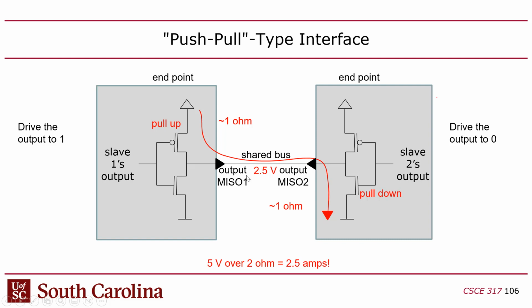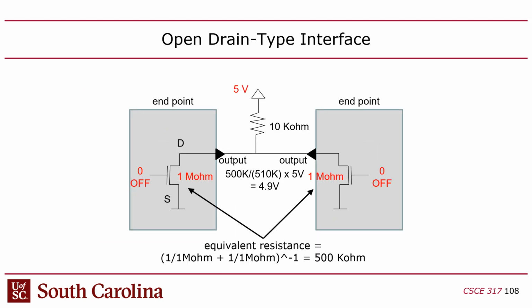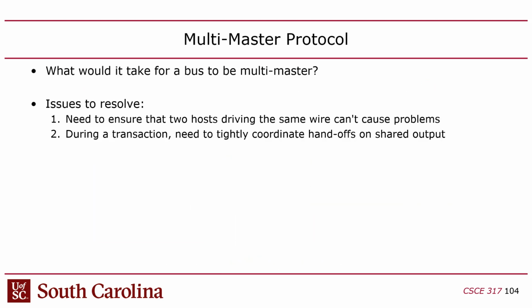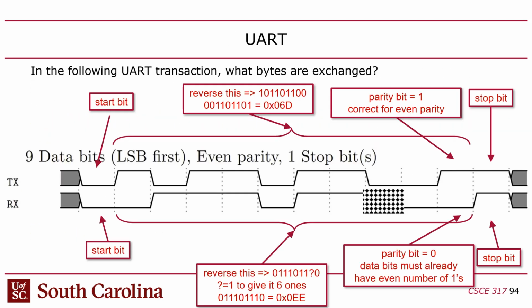And the effect is that it'll put the voltage level of that wire typically somewhere in the forbidden zone between active high and low. If it's a 5-volt system, it might put it in the middle at 2.5 volts. So one, you have a lot of current flowing there, and two, the signal of the bus would be undefined.